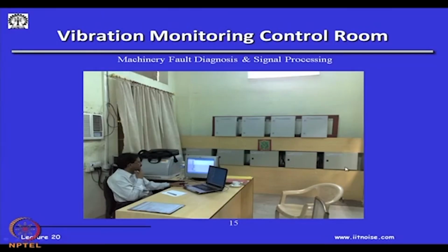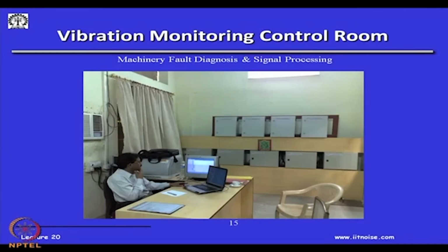Okay. And then all this signal comes to a monitoring station, wherein an analysis person could be recording and analyzing it, and there are automated alarm levels according to the standard. Whether the levels are high or low, they will let you know that we need to take precautions to reduce the levels of the signal and so on. And that is what is done in the monitoring of the bearings in paper mills. Continuously we have to do that.